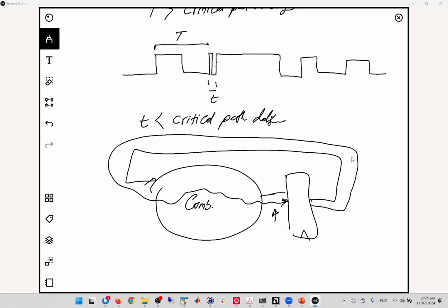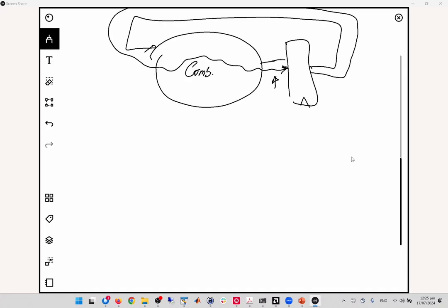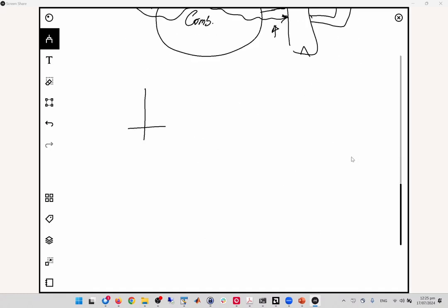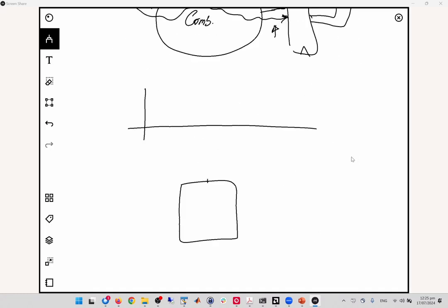Another one is also very well known as the power glitch. For example, you have your chip, and this is the VDD of the chip, and ground. And then I have VDD here over time. For example, the VDD should be 1.2 volt, something like this over time. But then at one point in time, I make it lower.